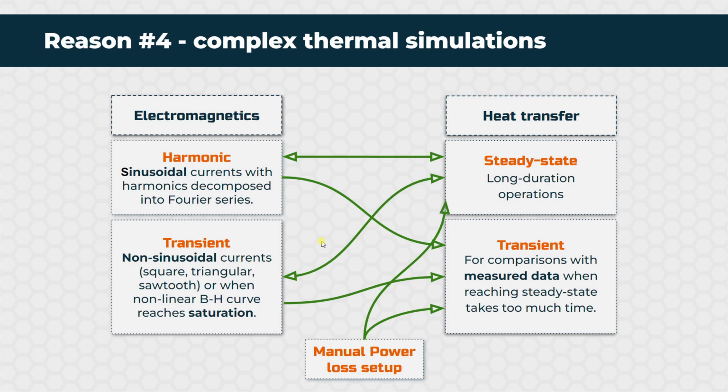If we try to simplify, then the next type of thermal simulation that could be used with FEM is basically solving heat transfer within the solids and approximating, with some boundary conditions on the boundaries, the heat removal from your component. And this is how TRAFOLO treats heat transfer problems. So you can feed losses that were computed from harmonic or transient electromagnetic simulation into a steady state or transient heat transfer solver.